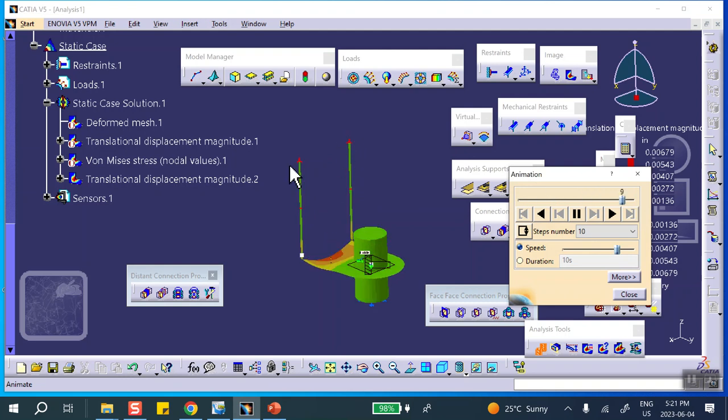There will have been differences on the top here, but I basically turned that thing into a hook by saying the three translations are fixed. The thing is that with a hook, or a pin, it's allowed to spin about the Z axis. I took away that. If I don't, then that may not run.